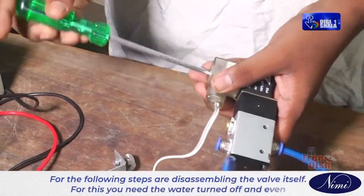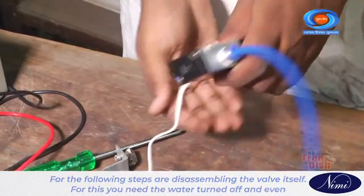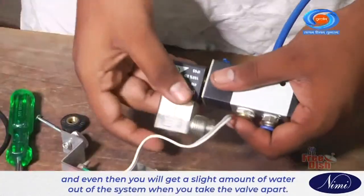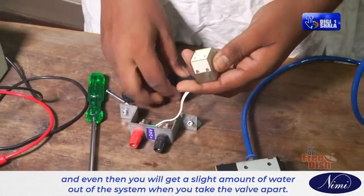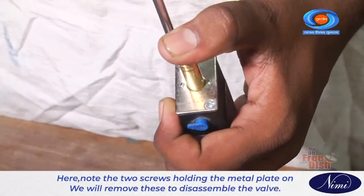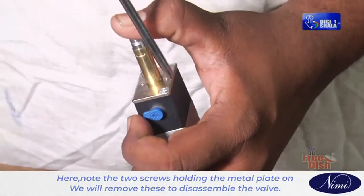The following steps are for disassembling the valve itself. For this, you need the water turned off, and even then you will get a slight amount of water out of the system when you take the valve apart. Step 3. Here, note the two screws holding the metal plate on. We will remove these to disassemble the valve.